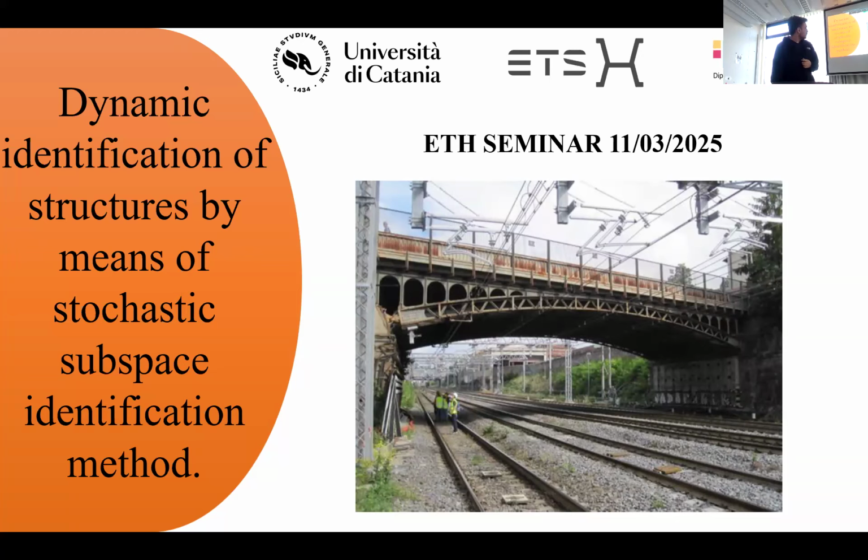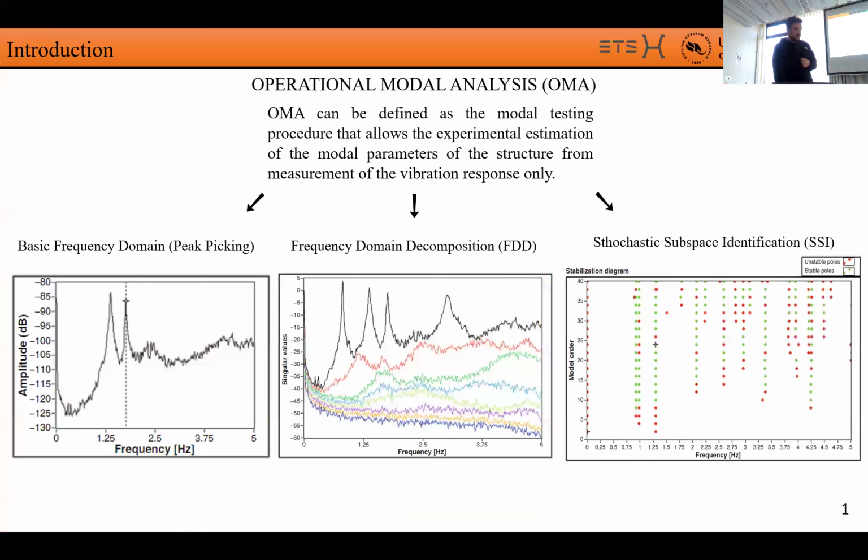So my focus is on OMA, operational modal analysis. We could describe operational modal analysis as the process to obtain the modal parameters of a structure, basically using vibration response only. So using acceleration, displacement, and velocities in order to get frequency, damping ratio, and mode shape.